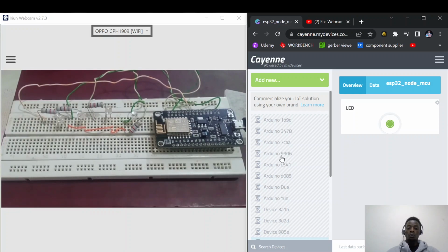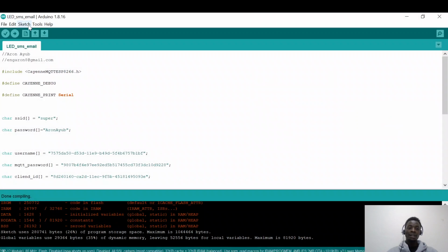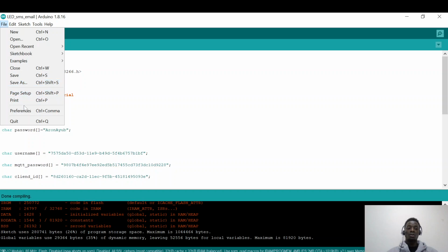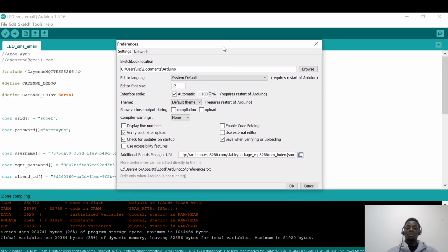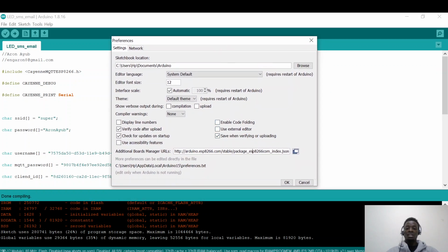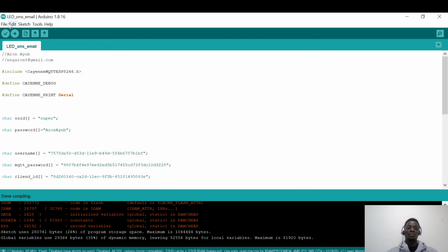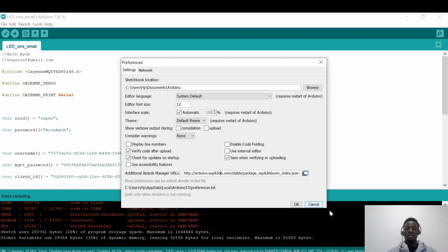What you need for this project is the Arduino IDE. First things first, you need to install the ESP32 libraries, that's the board libraries, and the Cayenne libraries. For you to do that, you need this link. It's in my previous video. Please visit it and check it out there, and you have to insert the link here. Just come into File, go to Preferences and insert your link here. After you insert your link, just say OK.